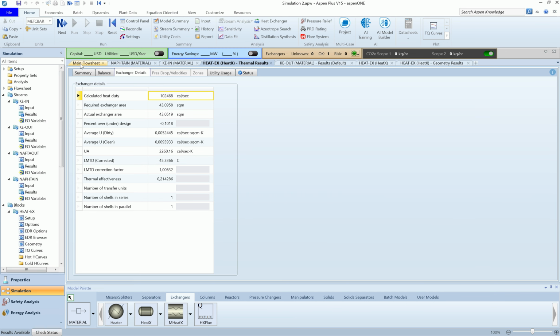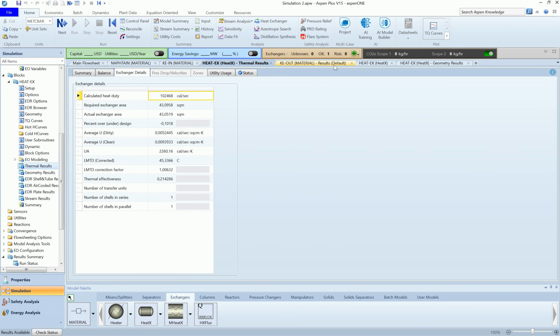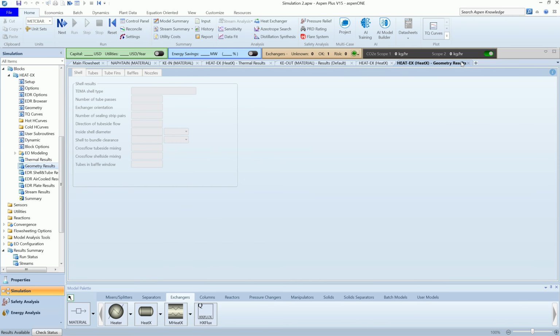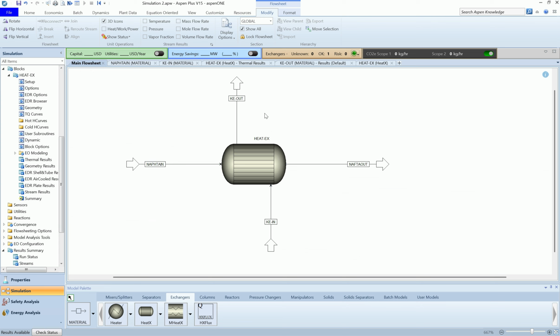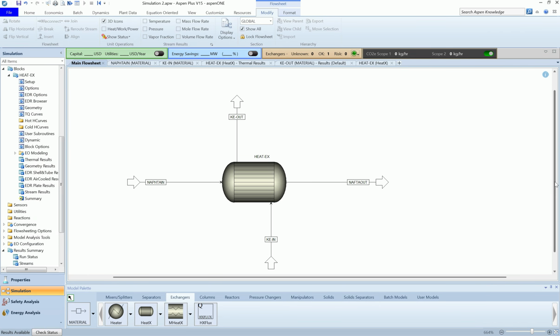Okay, so I think here we can try many case studies, we can simulate many heat exchangers, and also we can try other kinds of heat exchangers. You can try to use plate if you want, specifying the number of plates, the size of plates. Okay, and you can try to simulate other conditions. And also of course you can try to use different fluids, and maybe in the next study design a heat exchanger for heat integration in other studies in your research if you want.